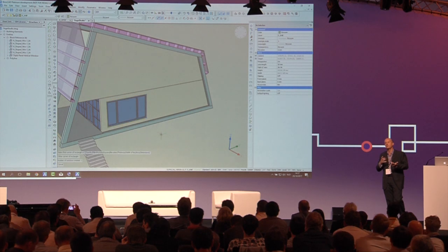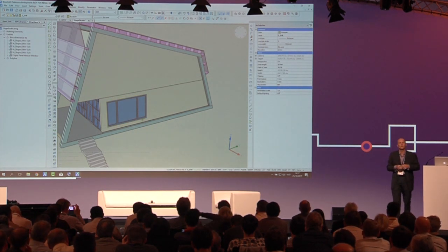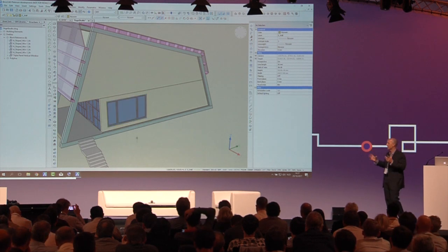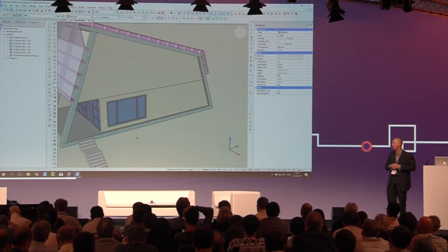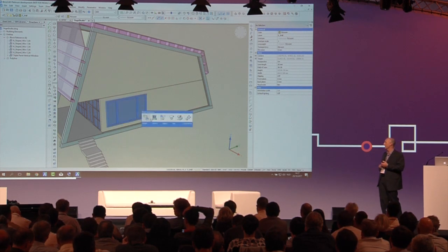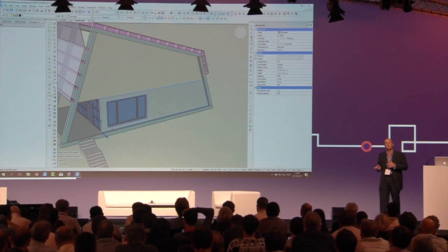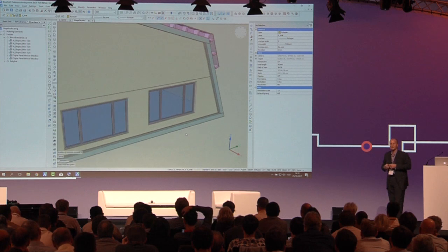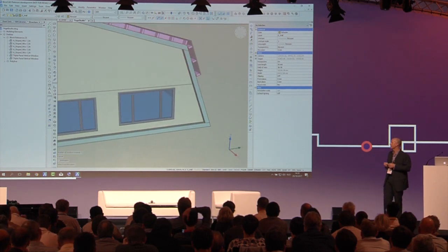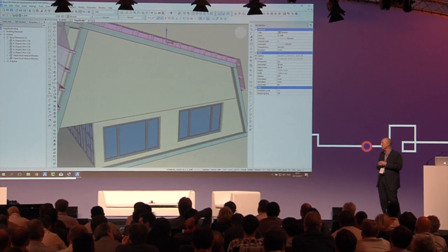And it also gives you a parametric window that you can build from as well. If you wanted to add other constraints to it to add even more capabilities to it, you could. Now, we can also use BIM insert to, if we highlight that window, then if we make a copy of it, it keeps all those same parameters, all the same values that we entered associated with the window that we've just created. So it's a quick way to get a lot of the same pieces in place.